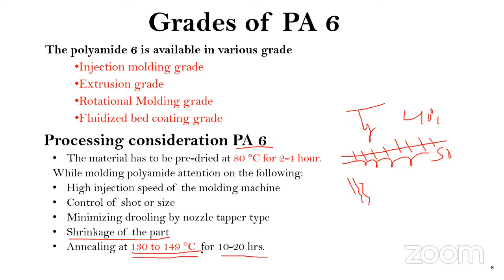Actually, in our company, we do annealing. It's a post injection molding process. After injection molding, the product will be a little harder, and it will tend to crack if a load is applied. To soften it, like metal, this annealing is done. Yeah, for the softening.